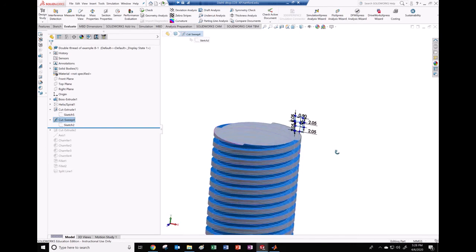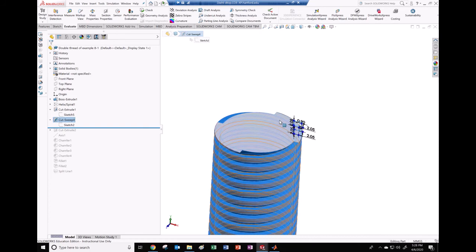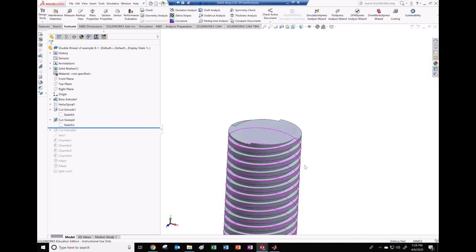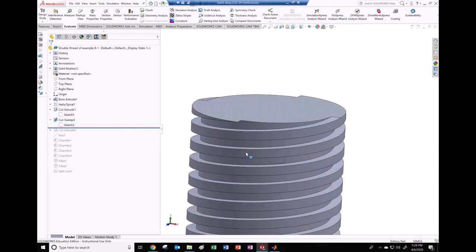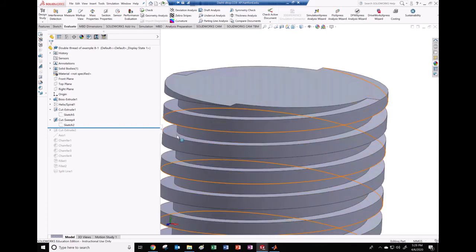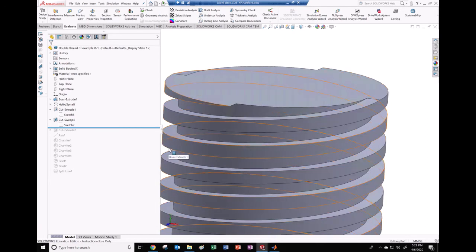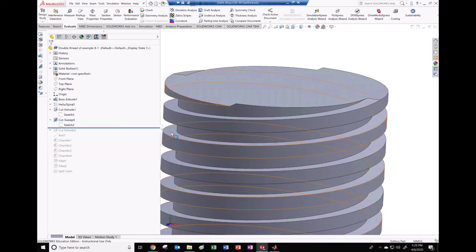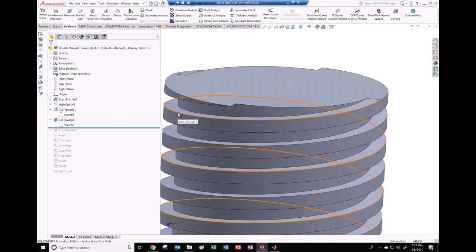So look at the top of this. You can see there's two places where it starts. And so these are running in parallel with each other. So now for every rotation, this thing is going to move twice the pitch. So the pitch is really just the distance in between the threads, right? From maybe this edge right here I'm pointing at to this edge, right? You want to not just talk about the gap, but also the gap and the thread, right? So that's the pitch. The lead is actually the full distance, which is going to be 2 times the pitch in this double threaded piece.